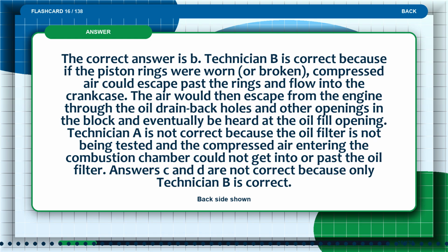The correct answer is B. Technician B is correct because if the piston rings were worn or broken, compressed air could escape past the rings and flow into the crankcase. The air would then escape from the engine through the oil drain back holes and other openings in the block and eventually be heard at the oil fill opening.